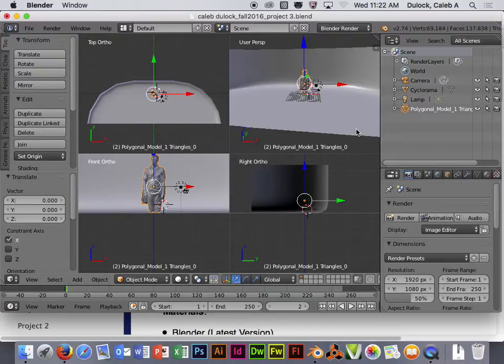Yeah, question? You can't open it. You have to import it. Like that's what we did last time, you have to import individual model files. They can't just be opened inside of 3D software because opening in a 3D program assumes that you're opening the format for the scene that you're working in, which is a .blend file. But instead, you would go to File, Import inside of Blender, and then you would choose the OBJ option if it's an OBJ object or an STL.